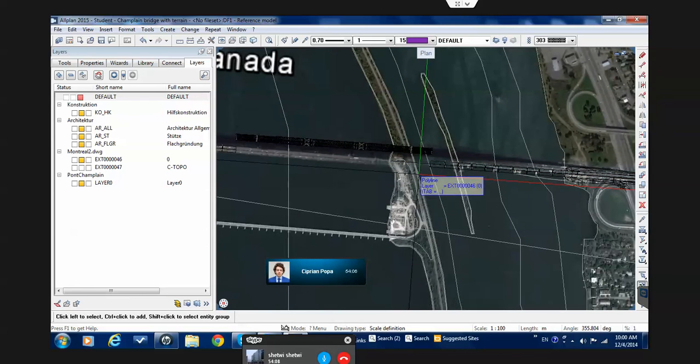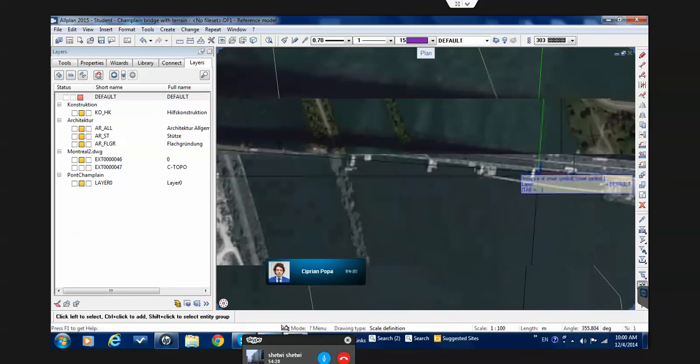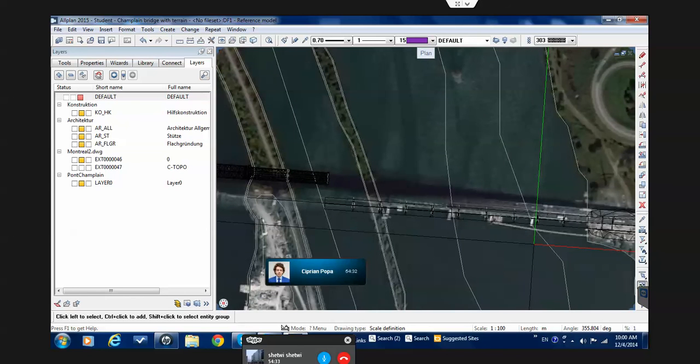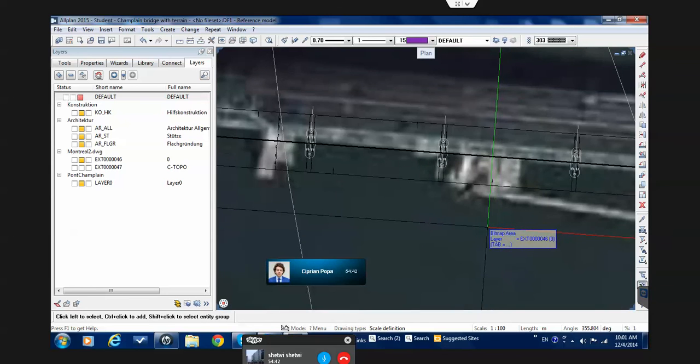And now, if you don't like the alignment I did with the bridges, no problem. You can do a line that crosses the bridge you see on the map, and the only thing we'll do, we will rearrange this, let's say this footing and the piles. It's no problem. The terrain will be the same, so if you'd like to be more aligned to this map from Google Earth, you can draw the line you need. Because it's no problem if you draw the line, we can do this copying of elements at the distance we need, so we can actually copy them with one click. We just mention the distance between them, it will follow your line.